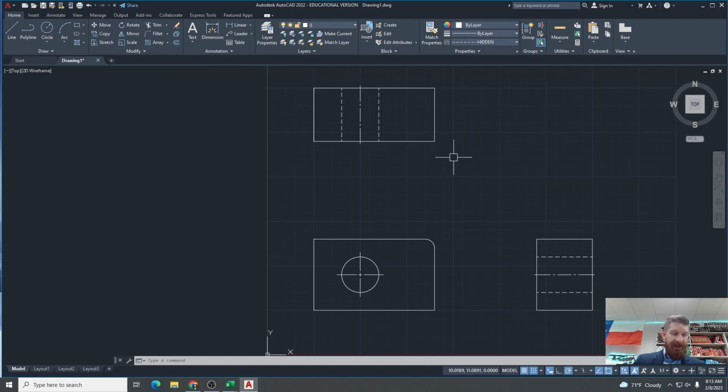So let's put a fillet up here. Fillet. We'll make this one a radius of 1 inch. So this side and this side. Would that change anything? Yes, that would change the curve of this leading edge here. You would see that only in the top view. So that's a fillet, right? Or what some people would call a round. Okay. A runout. Runout is just a visual representation of a complex fillet or round.